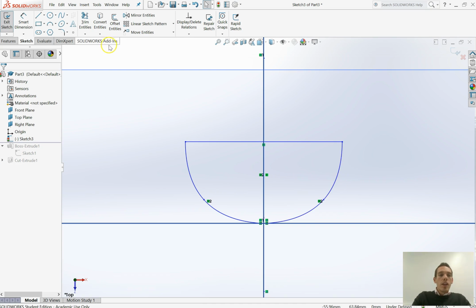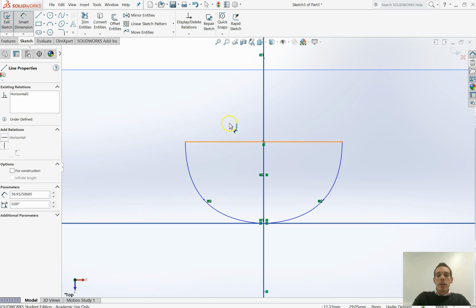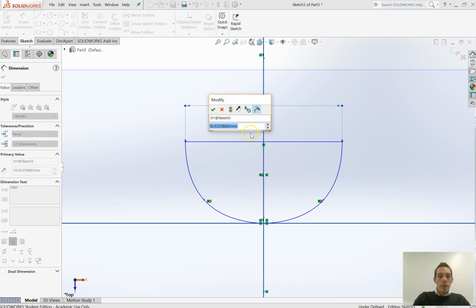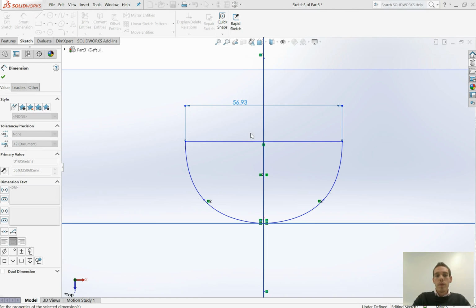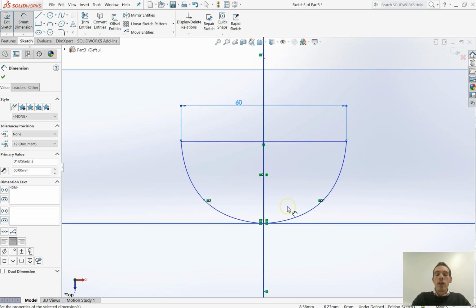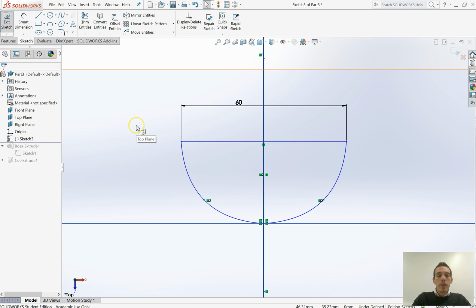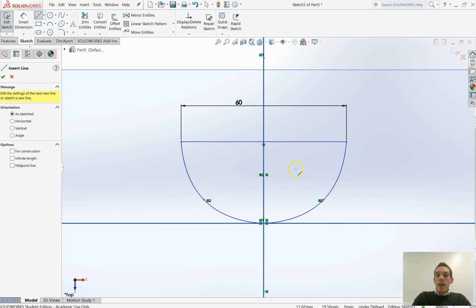Okay. So when we're building up things, we can use our dimensions to make sure we've got the correct dimension. That one would be 60, for example. We want to look at our relationships with other components, other lines, other sketches, and we also want to delete particular segments. You can just use lines to delete other lines, or to set up areas for deletion.